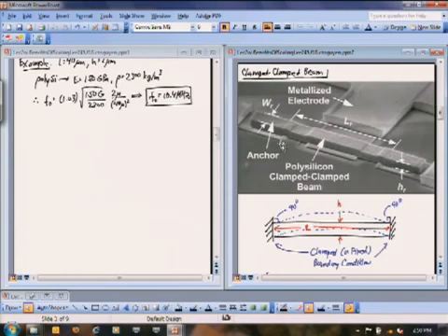So that's part of the process technology. We put these electrodes down first, and we didn't planarize the surface after we put down this structural film, so this structural film takes on these little glitches. You'll find that these little glitches will also knock the frequency down from 10.4 megahertz, but it won't knock it all the way down to 8.5 megahertz. Something else is actually doing that, and that is much deeper in the class.